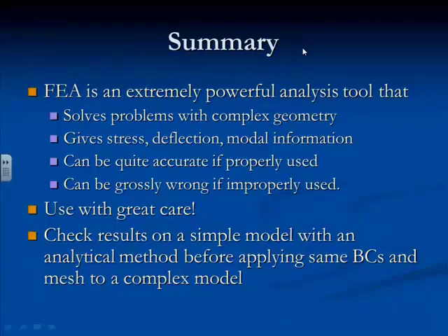But these packages, we're talking CAD solid modelers now, were created for the purpose of designing airframes because they were too complex to do with manual calculations. You've got wings with crazy airfoil shapes and tapers and whatnot, and the fuselage likewise. In parallel, others were developing FEA code, and they married those two, and that's why you can get away with 1.1 for a safety factor in an aircraft and not kill everybody, because the accuracy of the analysis is so good. But it takes a lot of effort and a lot of time and a lot of money.